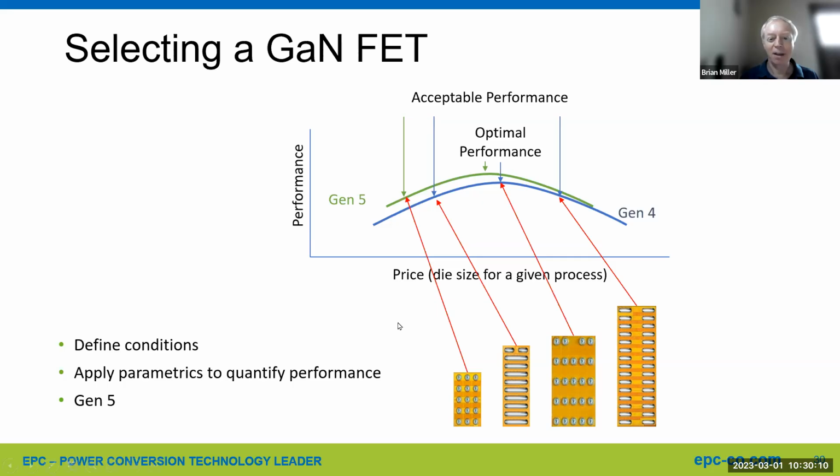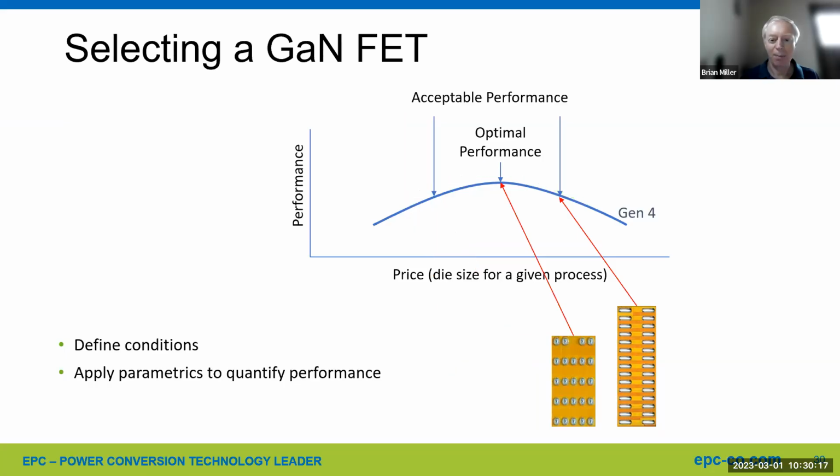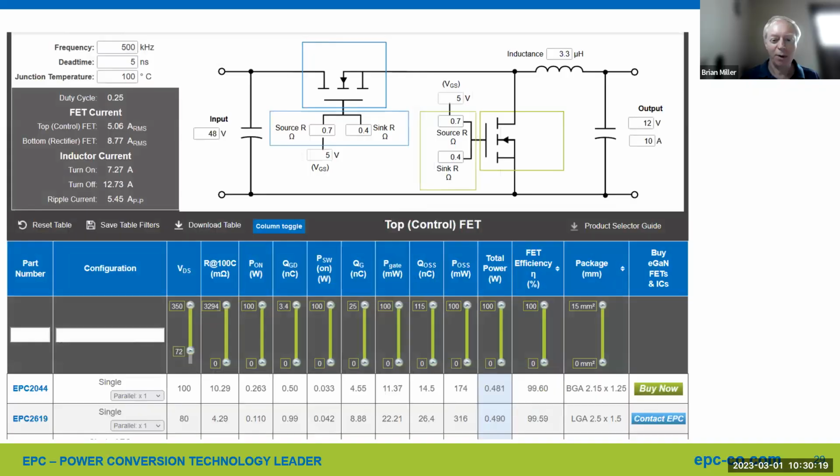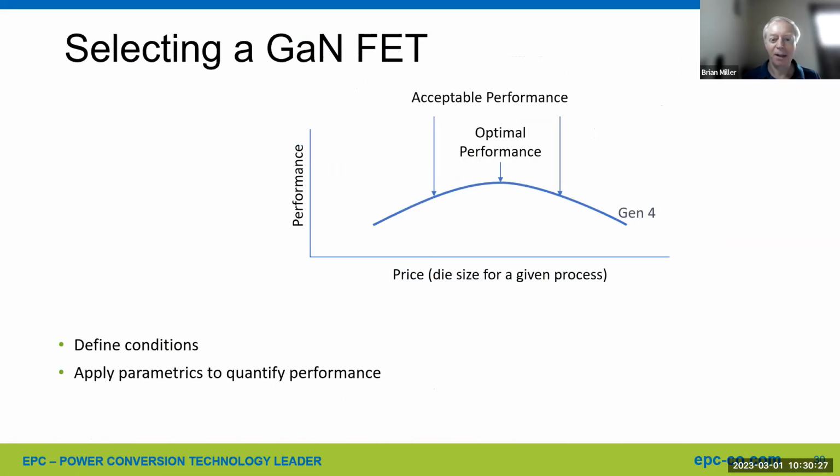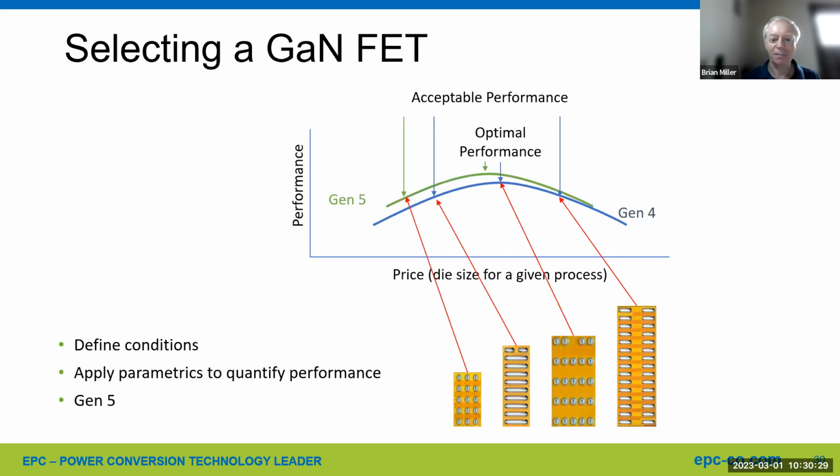So using something like that kind of idea, like the die size and the previous chart, which I'll go up again, showing a ranked order of the loss of the FETs can really help narrow in on good efficiency and also good cost using the latest EPC GaN FETs.